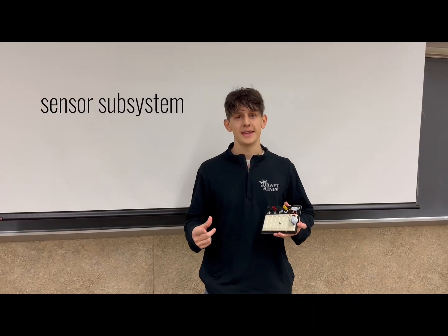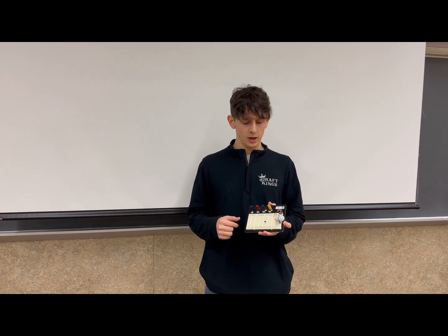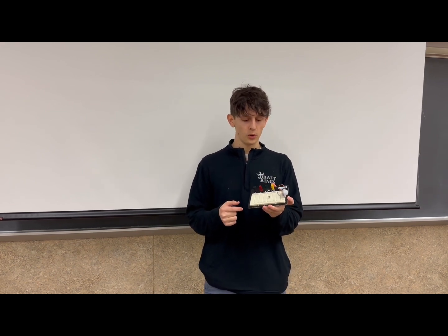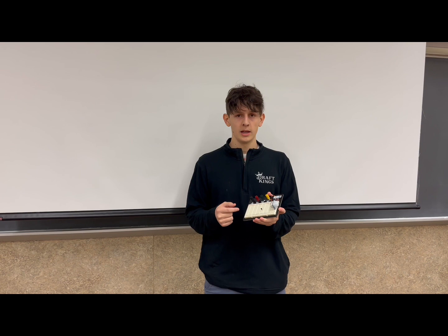Hello, my name is Tommy Gates, and I will be demoing my sensor subsystem of our design. Now I will be showing off how our temperature sensors and motion sensors work in each room. So in order to monitor the temperatures in each room, we will be using a Texas Instruments LMT87. And in order to track the occupancy of each room and when people enter or move around, we will be using a passive infrared motion sensor.